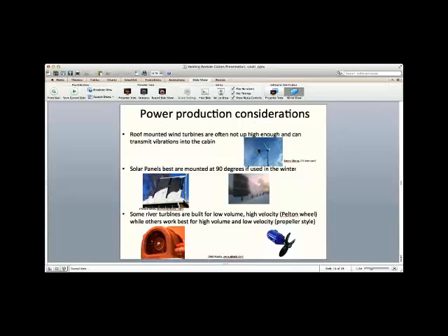So the thing that I want to just mention is, if you are going to go with batteries to store electrons that you could then plug in a 110 volt type of heater lately and get heat that way, you just want to be sure of a couple of things. Don't stick the turbine simply on the top of your house, but rather bolt it to the side of your house and then use guy wires coming out to secure it from all angles all the way around.